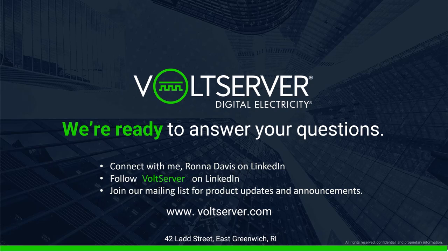Thank you, Rhoda. Next question is about efficiency. What kind of efficiency does fault managed power have or offer? Yeah, so fault managed power is a DC power technology, and we know that most of the equipment that we're going to be interfacing with in the data center is natively DC as well. Our power efficiency is very comparable, in fact, slightly more efficient than a traditional AC lineup in a data center. But it very much depends on what your lineup looks like. But we have done several models where we are comparable or slightly better than an AC power distribution.